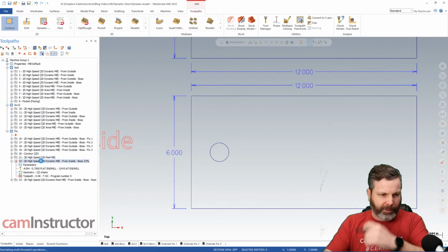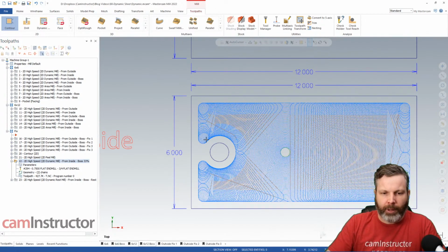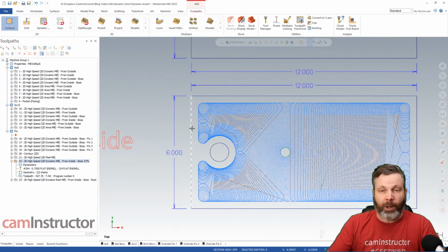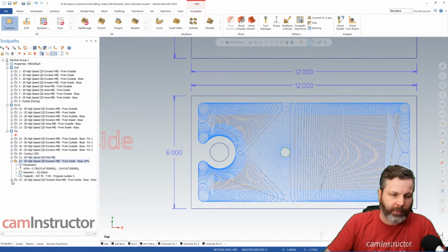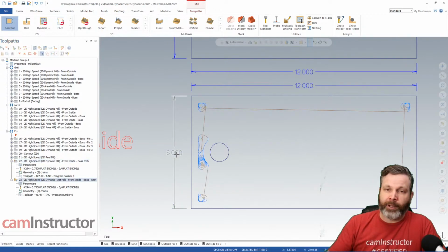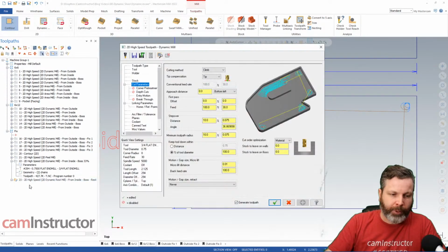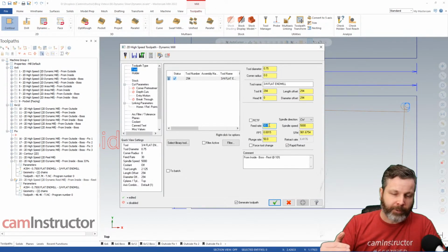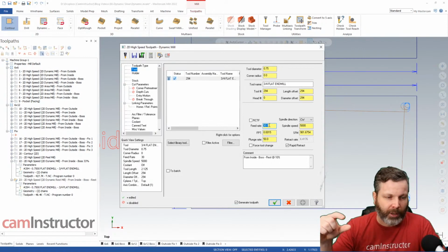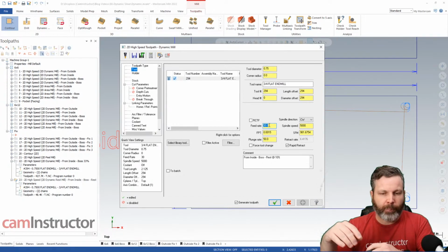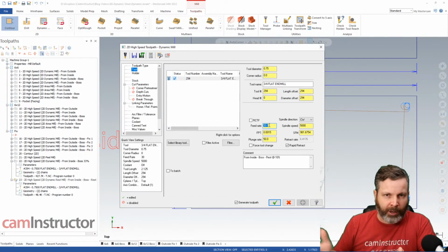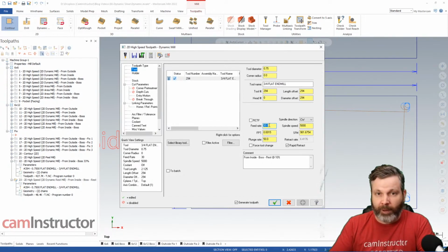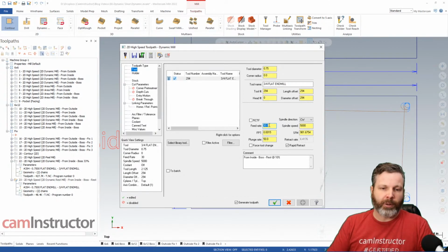Give this a second here to regenerate. And we're not going to get into this area now, so I'll make a second tool path that hits only those areas, and in this tool path, I'll force my feed rate down lower, closer to what something safer is. So theoretically this will take longer in your cycle time, but if you're breaking cutters going at 100% feed rate the whole time, this obviously is faster than switching out end mills